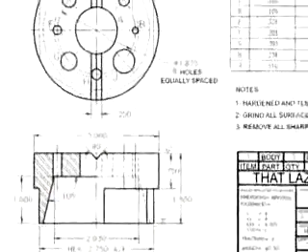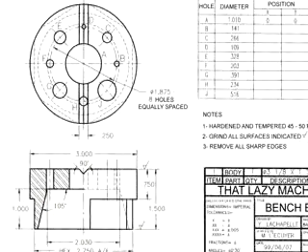And if we come back to the rest of the drawing, we notice something that's a little bizarre. There's no section line in the front view. And that's okay, because if what we're looking at is clear and obvious, no section line is required. In this case, it's a half section, and half sections rarely require section lines because when we look, in this case at the bottom view, the direction of view is clear and what has been cut is also quite clear because we can see both sides.